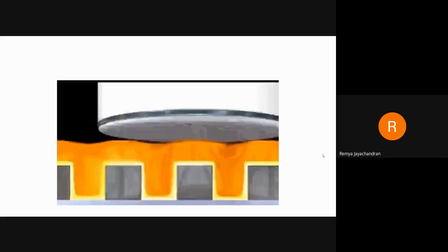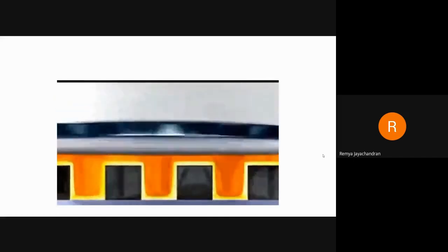Before that can happen, however, cleaning is essential for wafers, as particles lurk at every stage in the manufacturing process. There is a chemical mechanical polishing. Before the copper is poured into the trenches for the interconnects, a barrier layer is applied. It helps to avoid short circuits and guarantees reliability. The trenches are then filled with copper. Finally, the excess copper is ground down to the edges of the trenches.